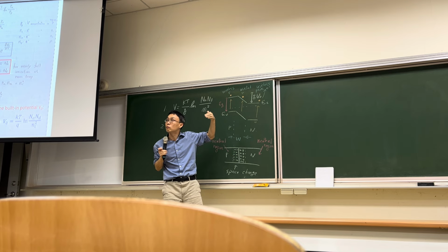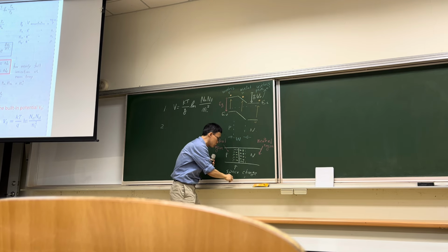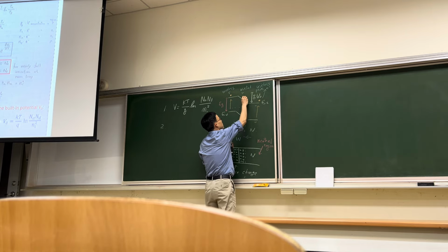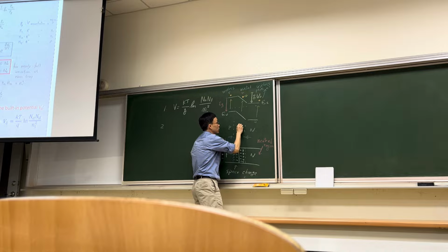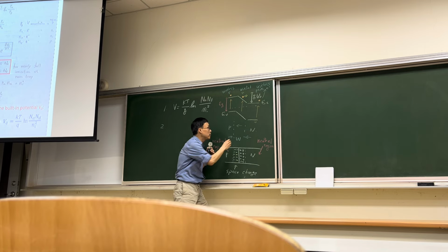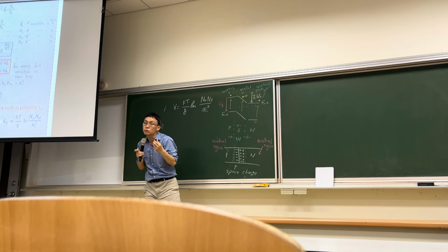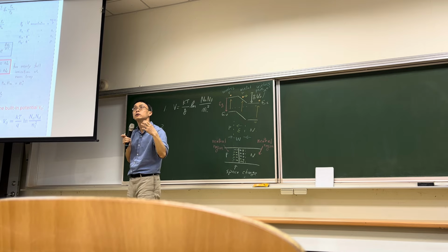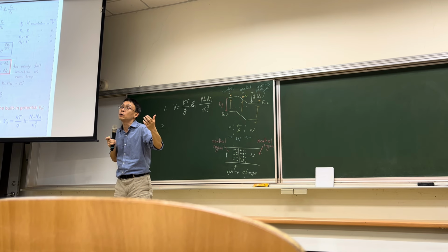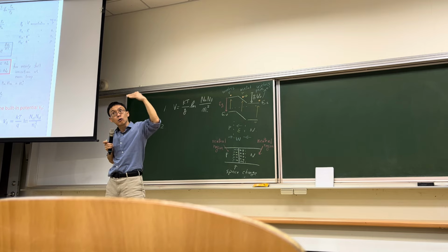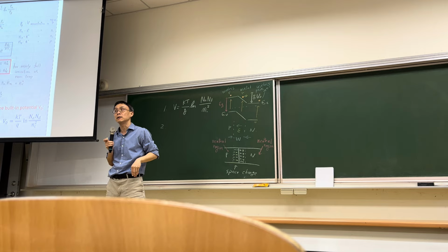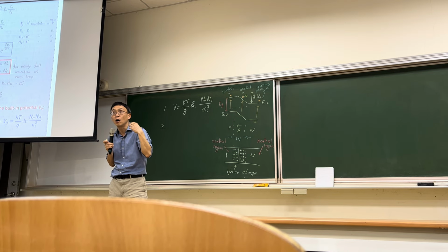Because they can move in the same direction due to the electrical fields created by this space charge, right? So I'm just telling you, if you can make this region wider, you can produce higher photocurrents, which will give you higher quantum efficiency, higher conversion efficiency of a solar cell, right? So you can produce more currents with the same number of photons.